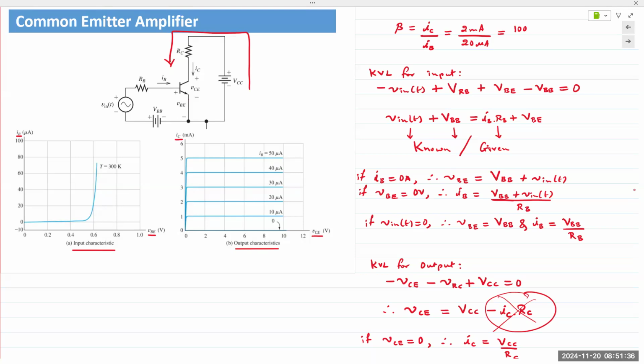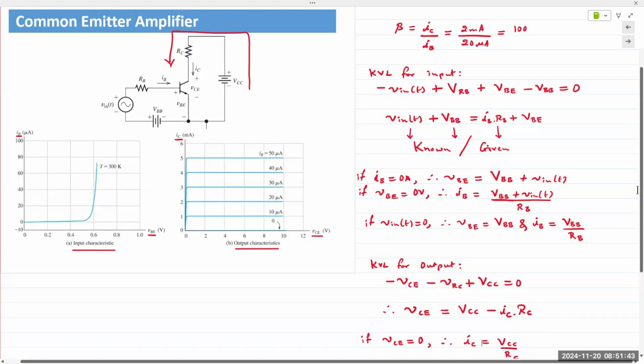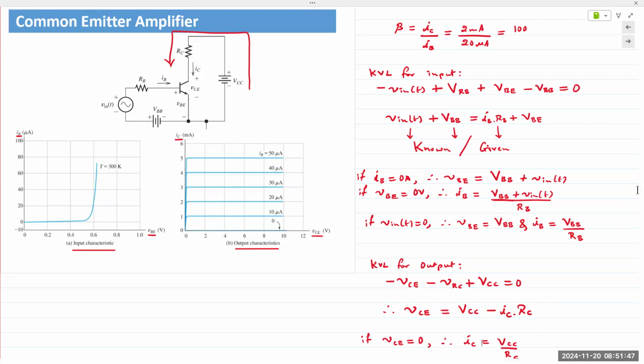Remember, a couple of classes ago, I stated we can think of amplification as the summation or the multiplication of AC with DC. In reality, what is happening is you have your DC flat line, and it's taking on the shape of your AC input. So if there is no input, the output is the shape of the DC, which is a flat line.